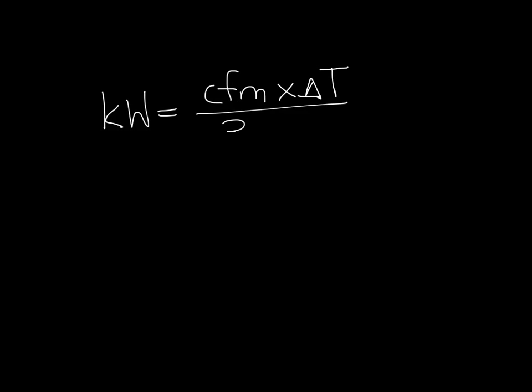The equation that relates kW, CFM, and temp rise is pretty simple. It's kW equals CFM times temperature rise divided by 3160. So let's look at an example.